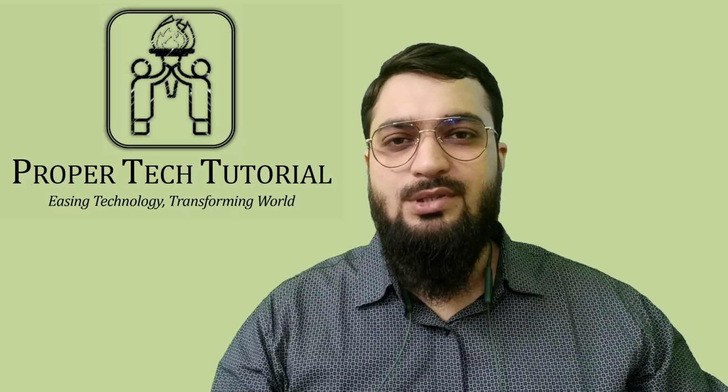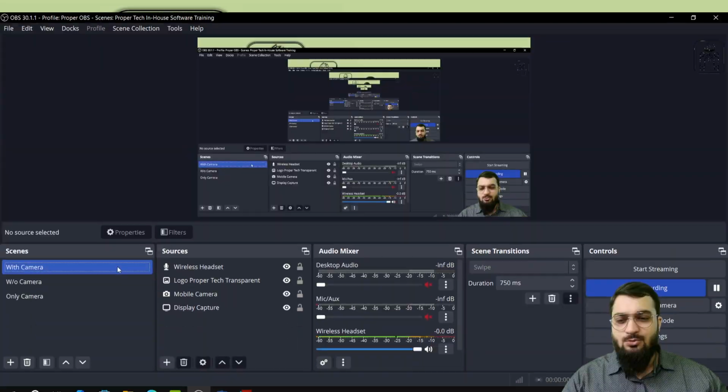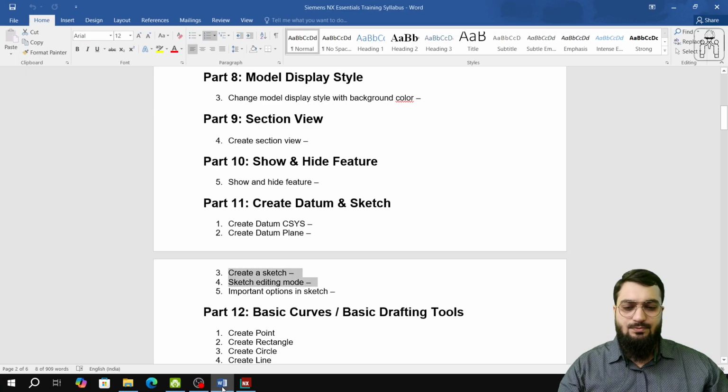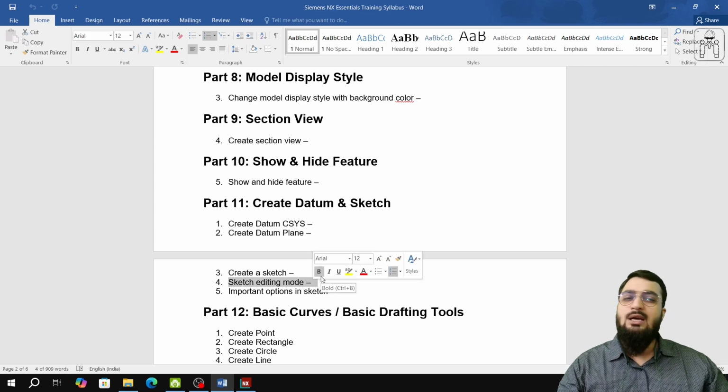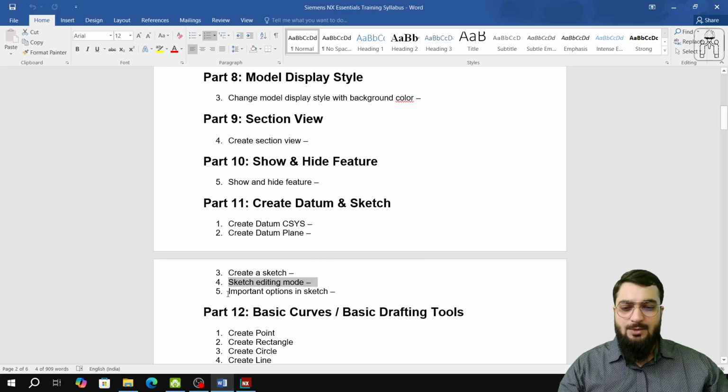And in this video we'll be starting part 11 and I'll show you the syllabus for your reference. So part 11 basically consists of creating datum and sketch, and the first two topics will be creating datum coordinate system and plane, and utilizing these two concepts you can create other things such as a datum axis, etc. The third topic will be creating a sketch and sketch editing mode. There are two sketch editing modes: one is the normal mode and another is the editing mode with rollback. And fifth are the important options which are available while creating or starting a sketch. So let's start.